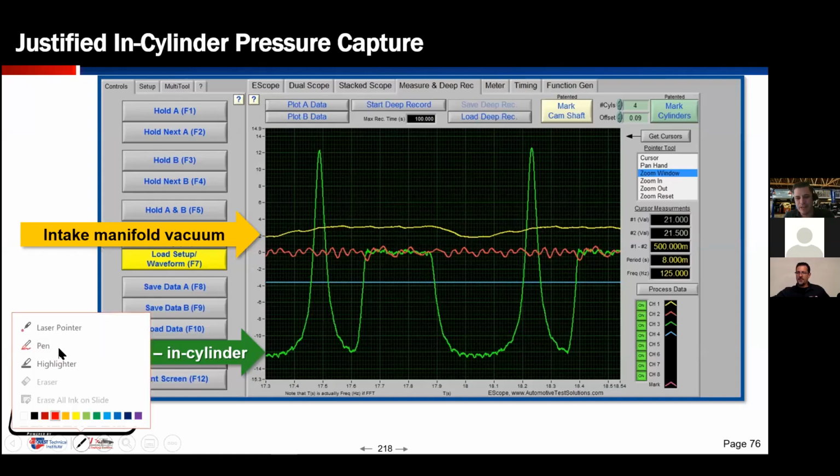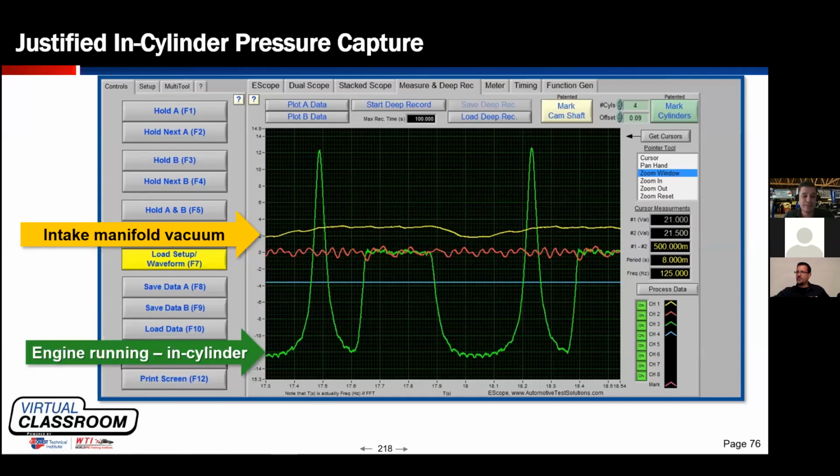Look at the pressure. There's no way an engine is going to create that kind of negative pressure in the manifold. Right. What we have here in this area, this is 10 PSI negative. So down here is about 14, which means this is about 12 PSI negative. And pardon my chicken scratch. This is really hard to do with a mouse. So here is about minus 12 PSI, which is about 22 inches of mercury, okay? Which is not crazy, right, for manifold vacuum on a good engine.